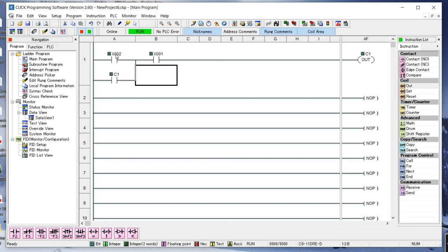The reason they do the switch in here, or change the order of the start and stop, is because with the PLC, it goes down and scans the first rung from left to right, and it's looking to see what is true or on and what is false.